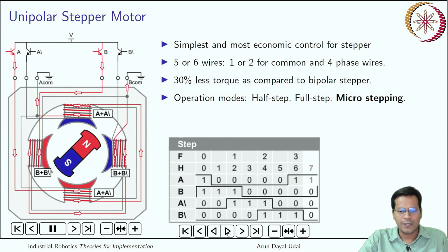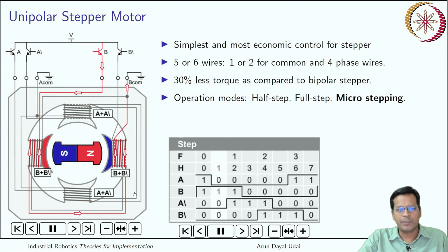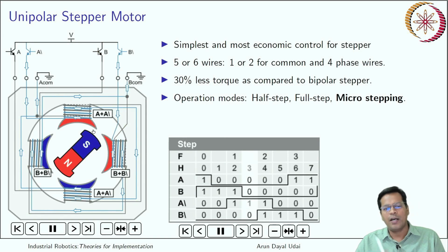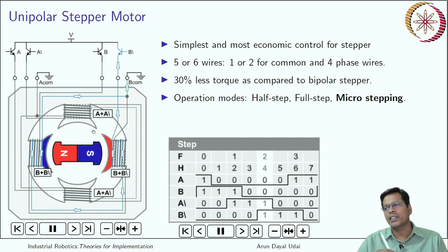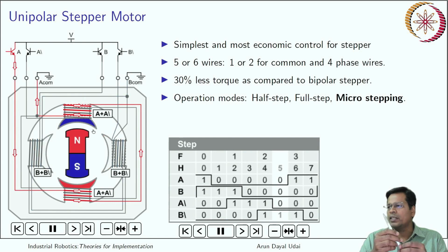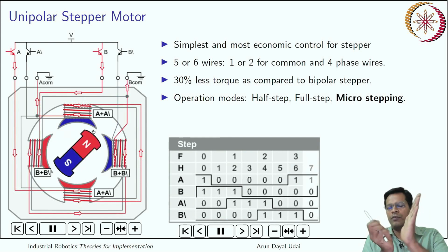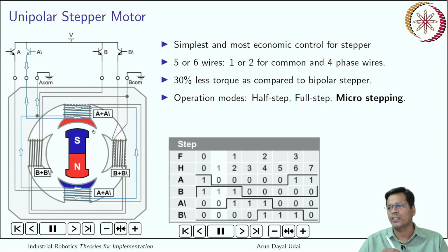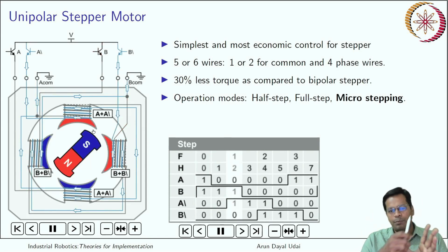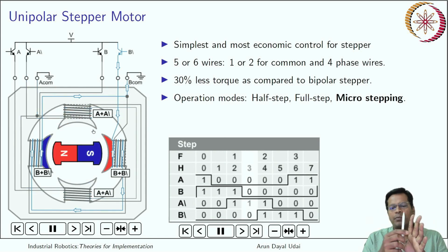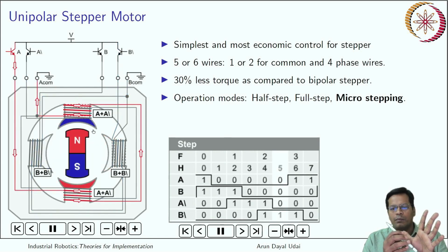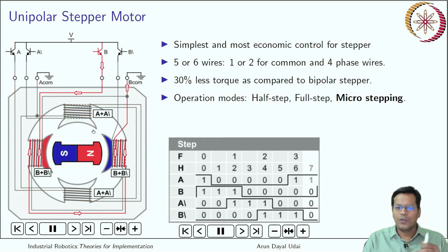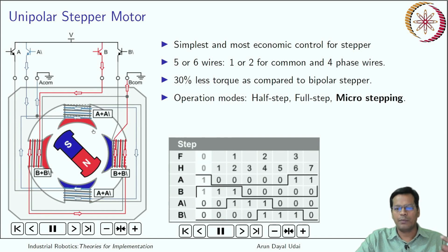So you see how it works. While it keeps running, we can discuss other things. In this type of running, when you have a number of poles, the armature is able to go even midway in between, because of energizing both the poles simultaneously. So that is half step running. One full step is pole to pole, and half step is pole, half pole, pole, half pole, like that. So it will rotate like this. That is what half step running is.